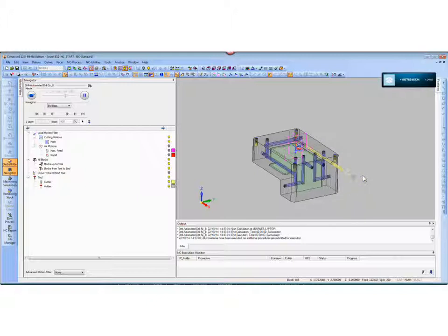You decide what drills you want to process with, and you set up the logic, and then you just apply the sequence, and it uses the logic that you build into it. And that's another thing I didn't mention was cost. Yes, these drills are expensive. They're a lot more expensive than a high-speed steel drill, but you have to consider the cost of the hole, not the cost of the drill. How long does it take to drill these holes, and amortize the cost of that drill across all the holes? Don't get sticker shock and say, well, that drill's too expensive, we're going to order the cheap high-speed steel ones. I understand that there's always limitations with resources, but please consider the cost of the hole, not the cost of the drill.